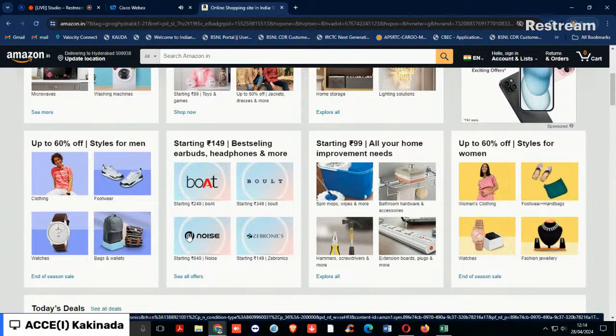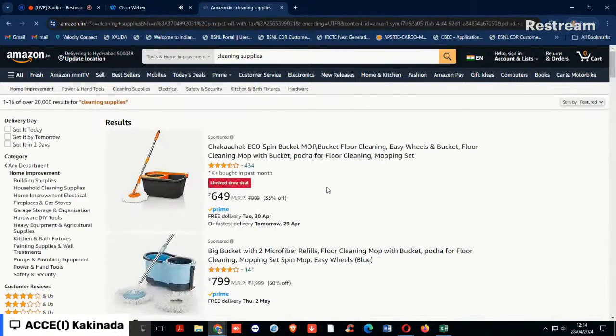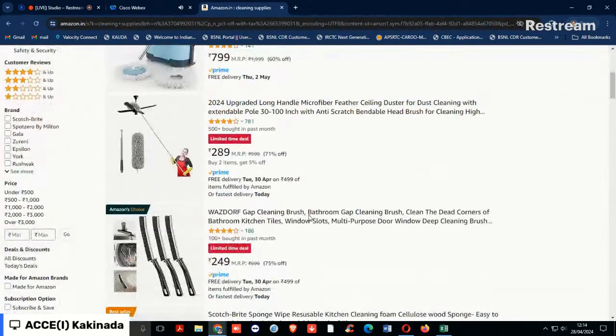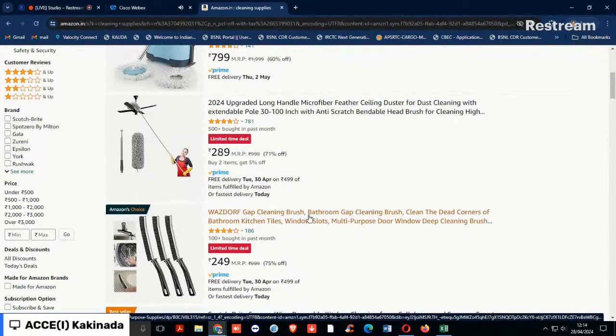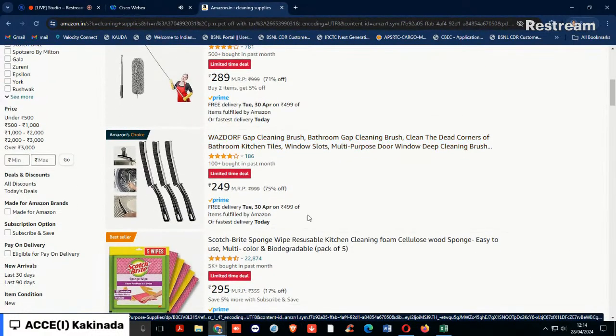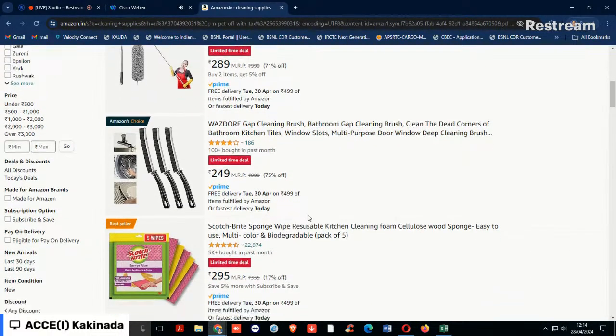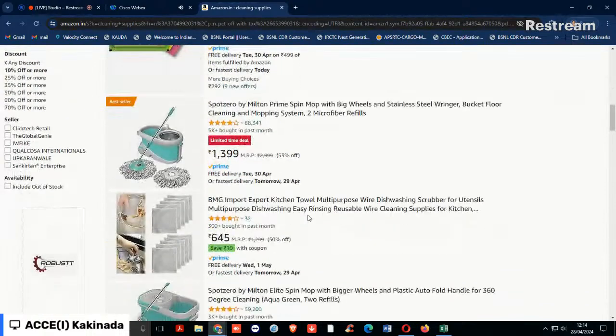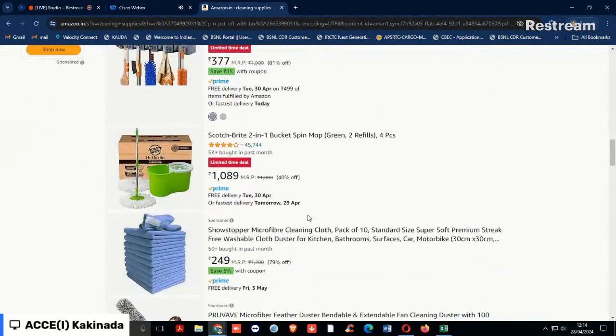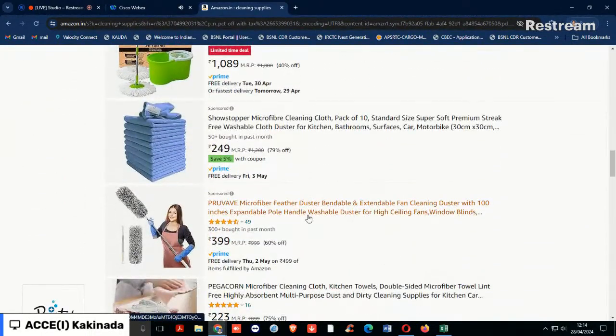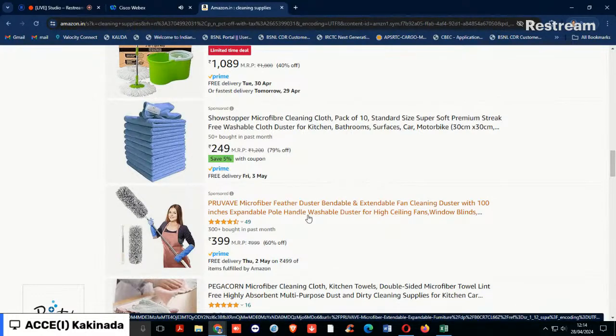Recently, we are seeing some video presentations of site fabrication of bar bending. That is also effective for small 6 mm diameter bars. At the site itself they bend with a simple lever. That gives better efficiency, leaving no gaps between the steel reinforcement and the stirrups. That is also a good construction practice. And these are the typical mistakes we generally come across with the usage of PVC conduits.